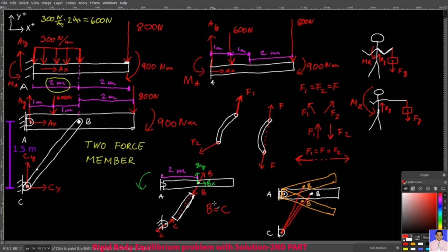Then the length of the BC rod would have to change as well, but it can't. It's rigid, remember? Furthermore, you have a smooth pin support at point B as well. It means that while it does not restrict rotation about point B, it does restrict translation in all directions. That's why, if the BC rod is strong enough, it will not let the main beam rotate.